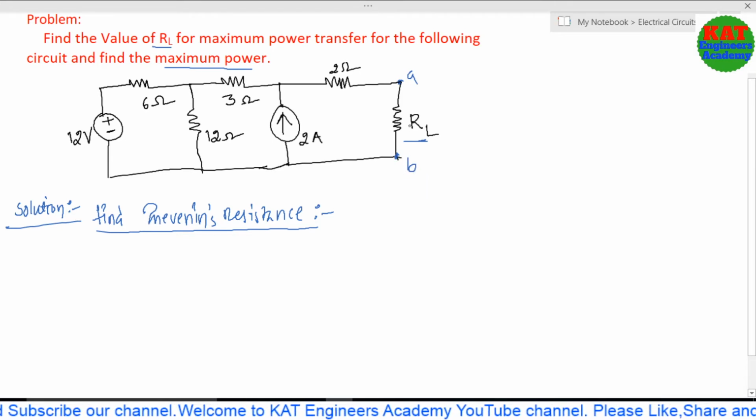In between these two terminals you have to calculate the Thevenin's resistance. You just have to open the load resistance and calculate the equivalent resistance in between A and B. That is nothing but RTH. While calculating the equivalent resistance for RTH, you have to replace the sources by their internal resistance. That is, the voltage source you have to make a short circuit, and the current source you have to make an open circuit. Like that you have to draw the circuit, and finally calculate the RTH.